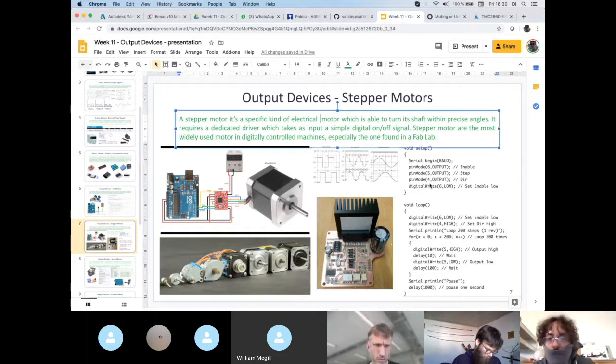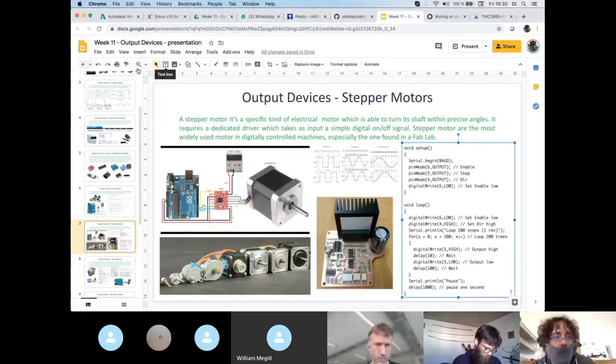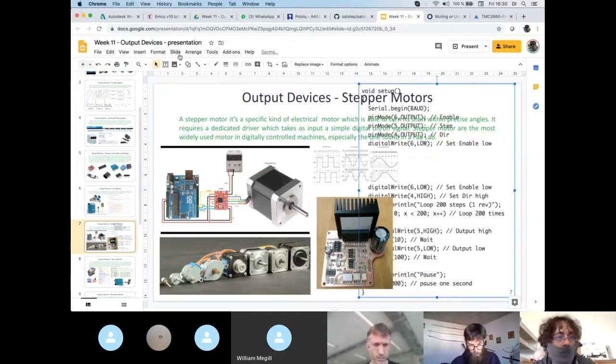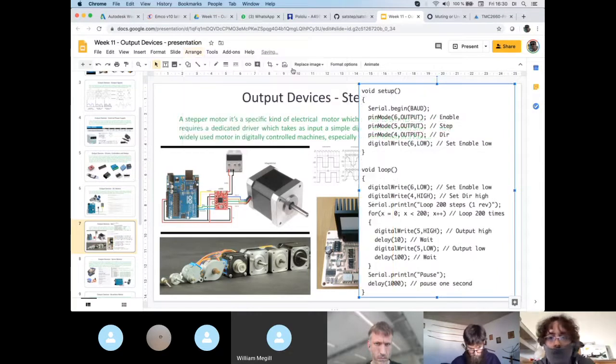So you can dig down deep in the datasheet from the stepper drivers and try to find your own stepper driver. So guys, how can we drive a stepper motor from the code perspective? I think this is also rather simple. So what we need to do is to connect these pins that we have. So in this case, for example, enable, step, and direction.